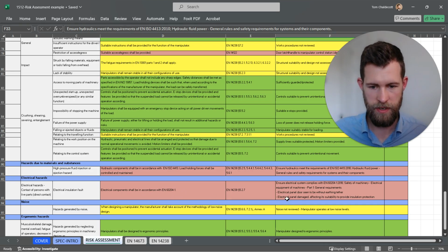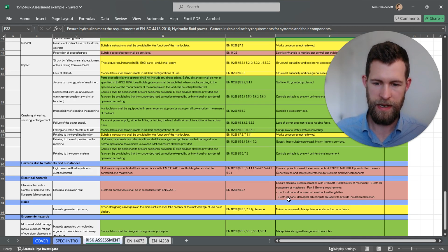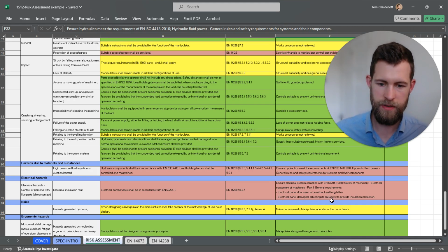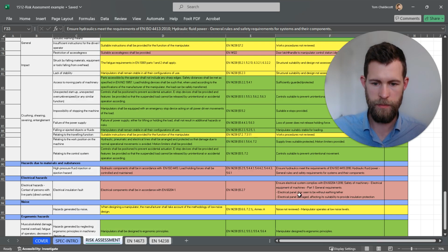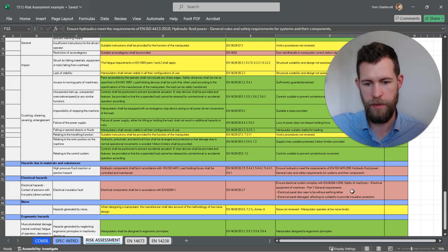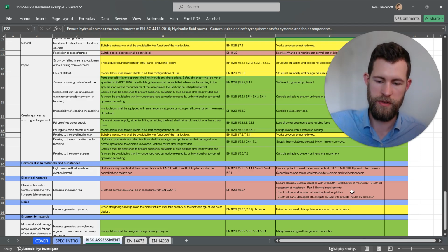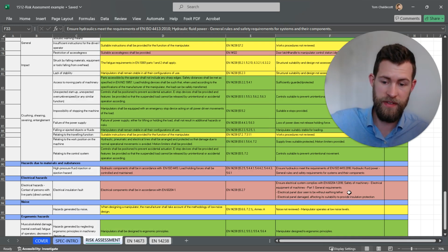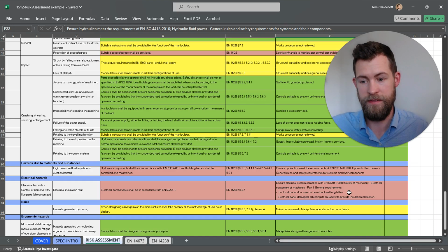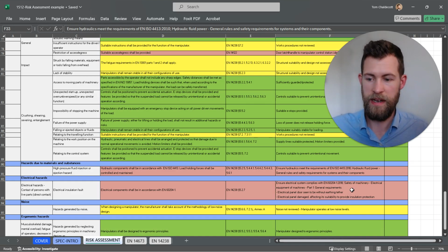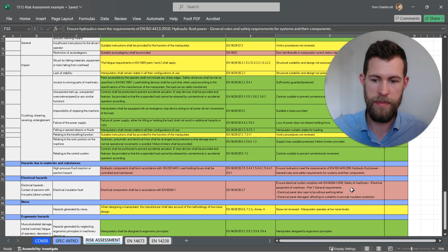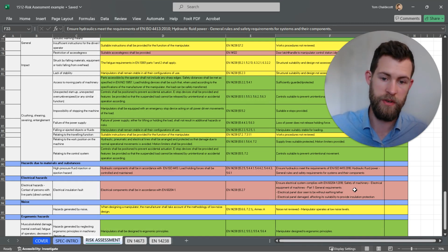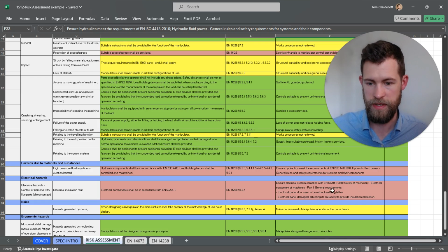Well, I observed two things. One, there was an electrical panel that was damaged, badly dented, and there was an electrical panel door that didn't have an appropriate tether between the enclosure itself and the door. So there are a couple of things identified there where, should there be further damage or an issue with the insulation, there might be a fault where someone would be exposed to live electrical parts. And that's taken from within the standard.